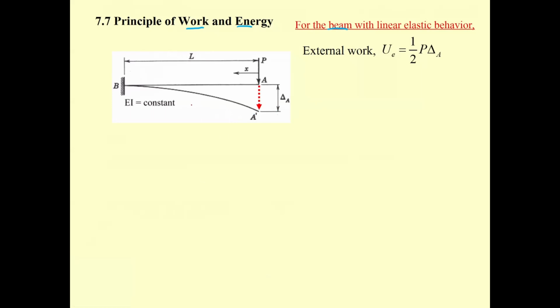So this one is fixed, no deformation. Theta sub B equals zero, and the vertical displacement v in the y direction, or x direction, also equals 0. And then the beam has this kind of elastic curve.